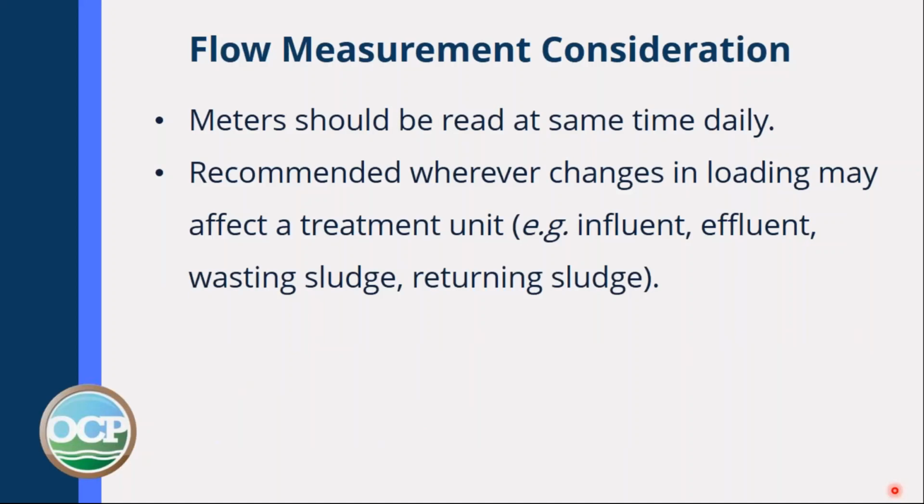Some other considerations for flow meters: read them at the same time every day. And if there are any changes that may affect the treatment of the wastewater, also check them.